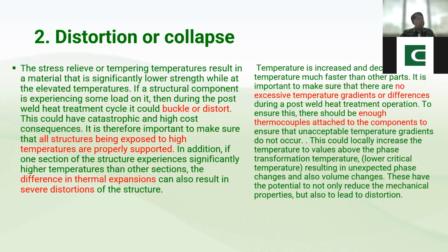Second effect is if you're heat treating a thin material, yung mga manipis na material, and there is a possibility of over temperature, therefore buckle or distortion can occur during heat treatment. So make sure to follow the heat treatment temperatures, heating rate, soaking time, and soaking temperature.